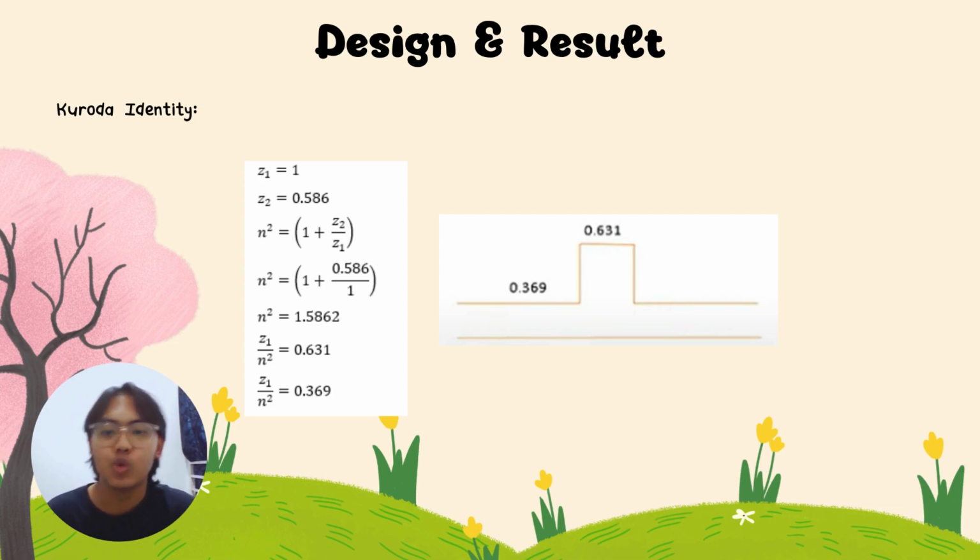Okay, this is a Kuroda identity. For this Kuroda identity, we use case one, which is a shunt stub followed by a TL, or transmission line. So Z1 is the transmission line, and Z2 is the shunt stub that we use from the Richards transformation. After we do this calculation, we need to draw it in series. So from the shunt stub open circuit, we get it into a series circuit.